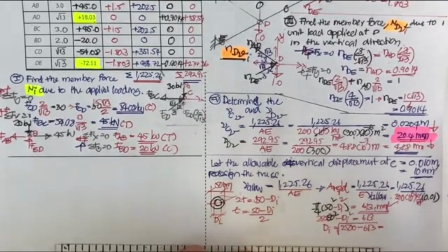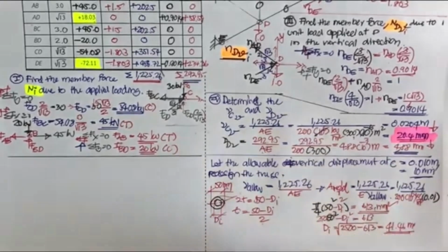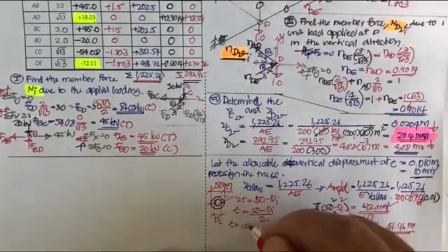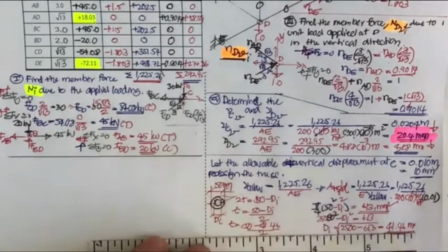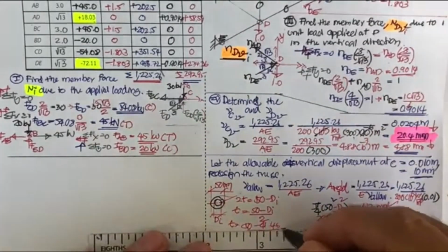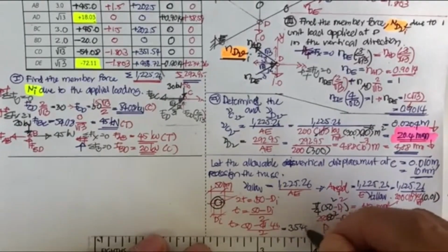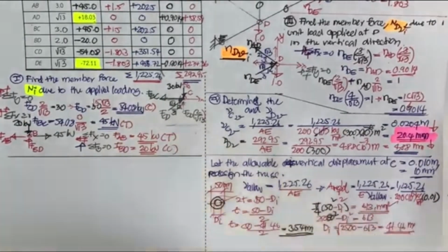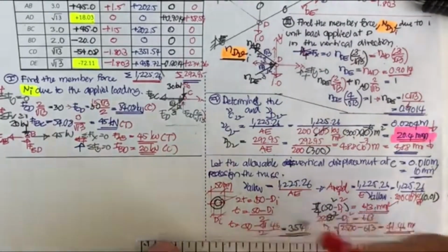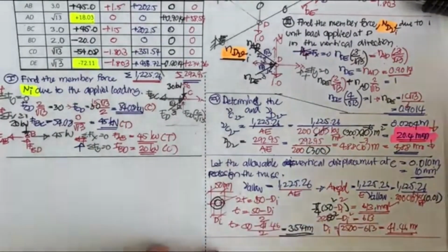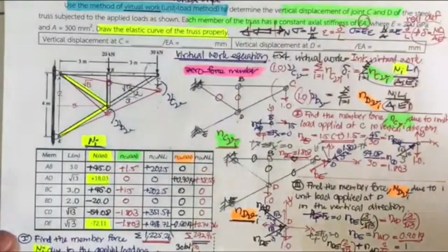You push it into your calculator. This is going to be 41.46 millimeter. That is going to be the internal diameter, and then t is going to be (50 minus 41.46) divided by 2. So you're going to have 3.54 millimeter. Just check what section is manufactured by the steel company, and you select the bigger one that's bigger than this. Okay, that is the end of this example.